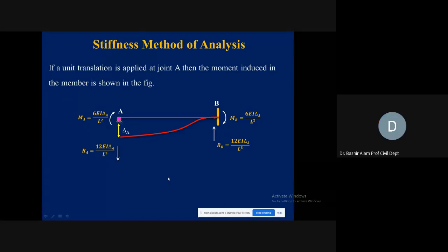You will be using this again and again, so you need to quickly find all these values. If a structure and a member are given, first you need to look at the I value, whether it is 0.5I, 2I, or 1I, and accordingly put that in the equation. If a settlement is given, you will have to incorporate the settlement and the specific length you are given, and put that in this equation.